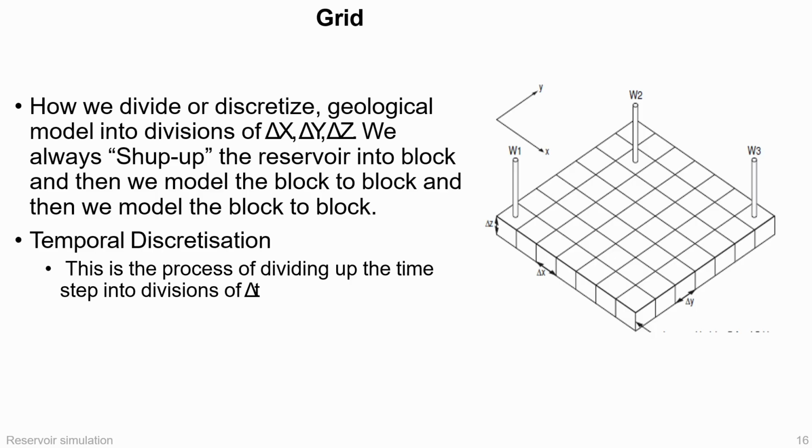The reservoir is not only distributed in space, but also evolves over time. Pressure changes, saturations change, and production changes. Therefore, the simulator must track both spatial differences and temporal evolution. A smaller block size and a smaller time step can give more detail, but they also increase computation time. Again, reservoir simulation is always a balance between realism and practicality.